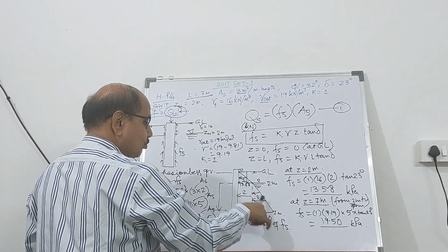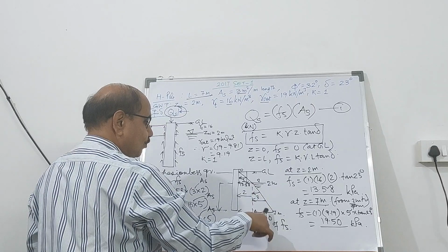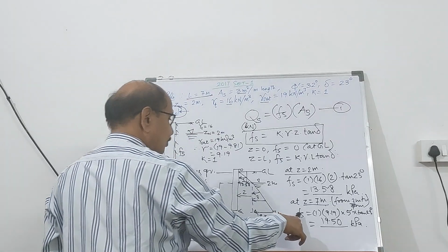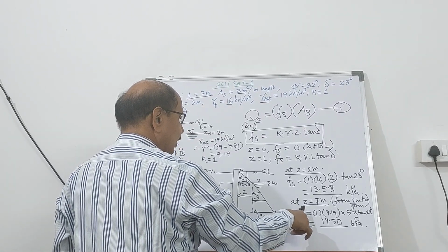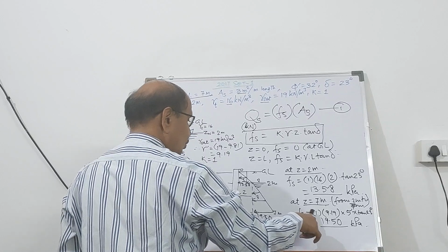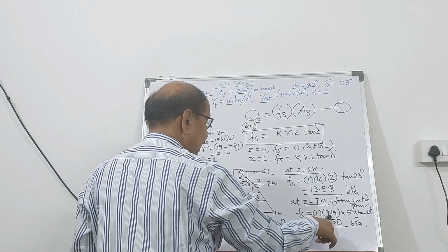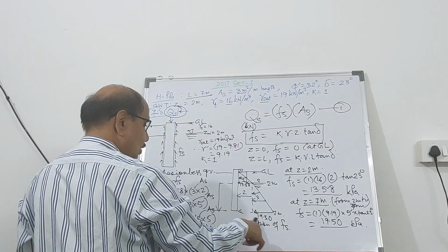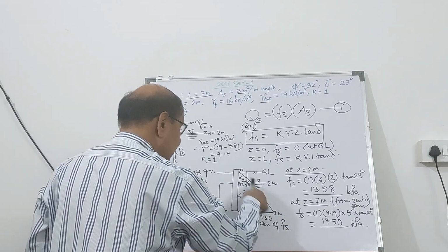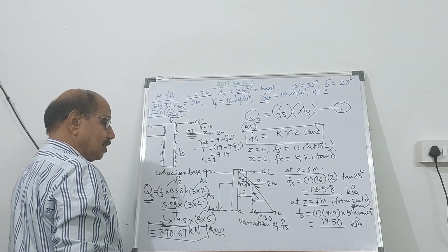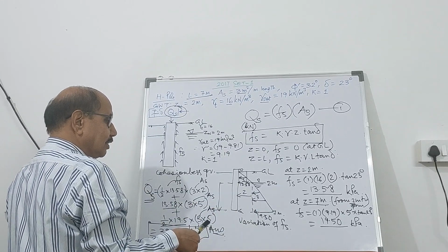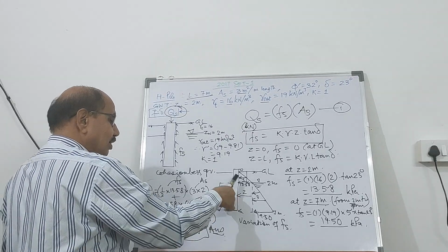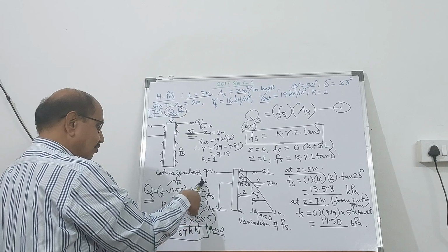And here the unit weight is going to change, from 2 meter to 7 meter. That is for a range of 5 meter. So for a range of 5 meter, you will have to calculate Fs. Fs is going to be k value 1, 9.19, that is the gamma prime, into 5 into 10, which is 19.50. So you get the variation of Fs over the pile's length, and then you can find out the value of Qs by multiplying Fs with the shaft area.